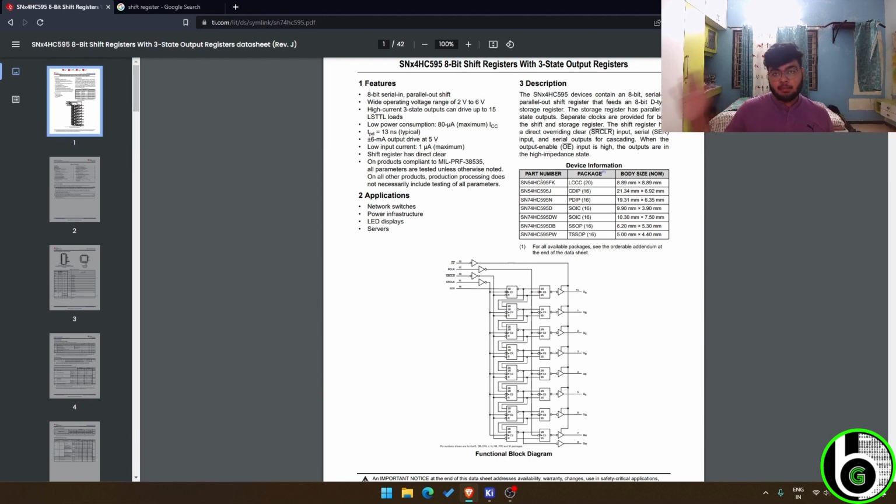Apart from that, there will be another playlist which will be completely about the physics behind PCBs. Apart from that, design considerations, why you should design a PCB in a certain way. Apart from that, a lot about even the kinds of components that are available. Say, for example, you get an IC. An IC can come in many different forms. It can be a BGA, it can be SMD, it can be a THT IC. So we'll discuss the different ways in which things are manufactured, and what you should be considering when you select a different type of package.